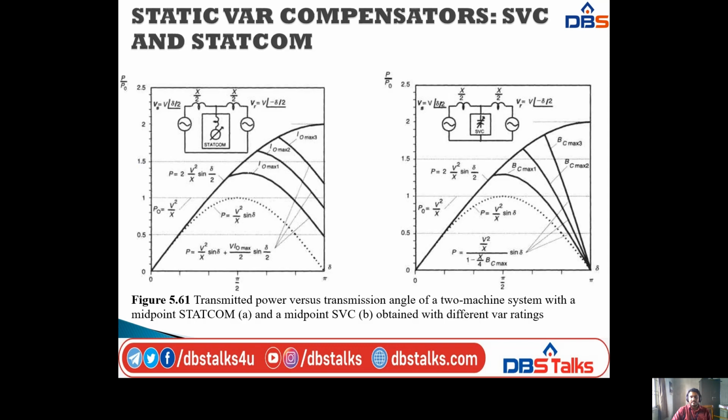Here, if you observe, I am taking the angle delta between 0 to pi and the power between 0 to 2.5, with the power values in per units. These are the different curves at different levels. We have P equal to V squared by X into sin delta, plus V into I_0 maximum by 2 into sin delta by 2. This is for all three curves, and P equal to V squared by X sin delta is for the dotted line curve. We have the half sine wave.